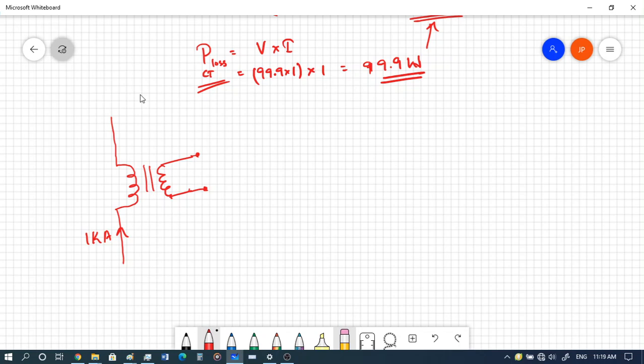If you want to change the range of the ammeter, or want to place a different ammeter, you don't have to touch the primary circuit. The primary circuit can continue with its functioning. You don't have to disconnect the circuit or anything of that sort. You can do everything from over here, and since you can use a switch over here, it is very easy.